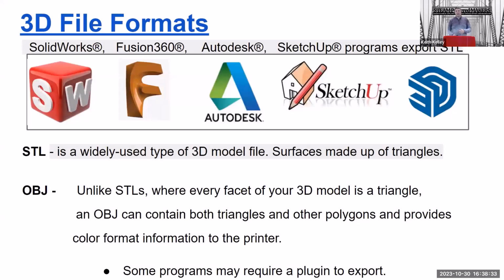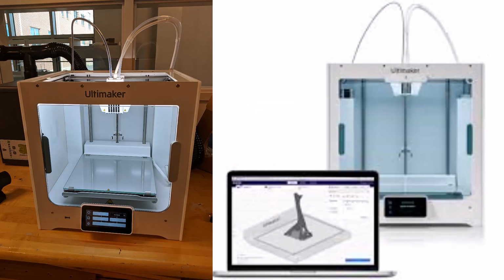Now, file formats, the big two we do are STL or OBJ. STL is the standard pretty much. OBJ, the only real big difference is if you have a printer with a dual extruder, not just one, you could say, print with the different colors, pause and change the print extruder. We don't. Most of the time, I'm not having kids do that. So we do it in STLs.